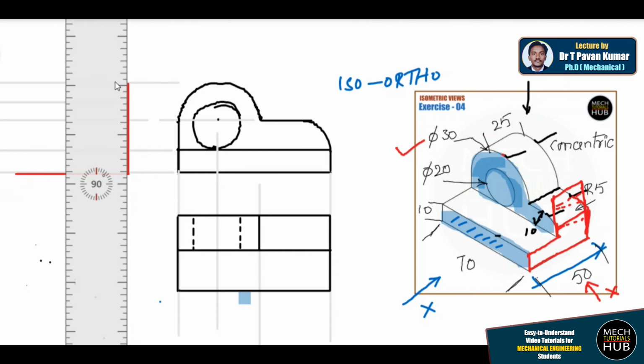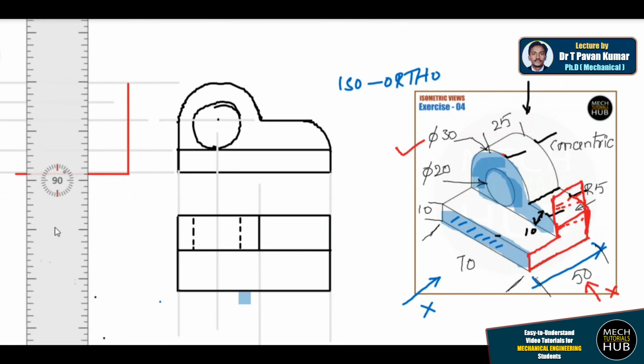This is what is visible from the right side that I am going to draw to the left. You need to maintain a width of 25, because the width given is 25 and the same width is visible here. Let me mark this as 25 distance and drop a line till the bottom second horizontal.